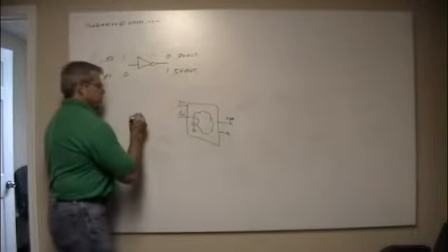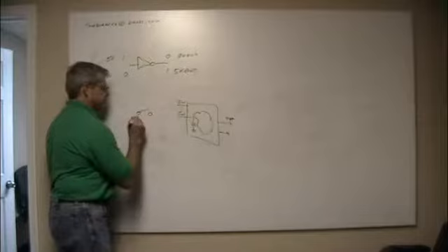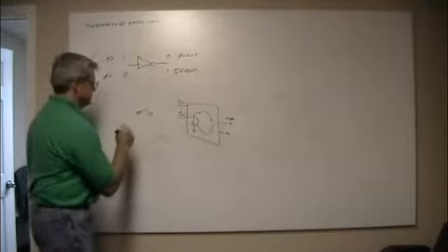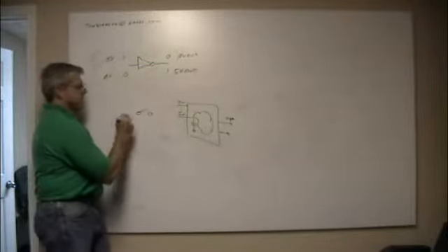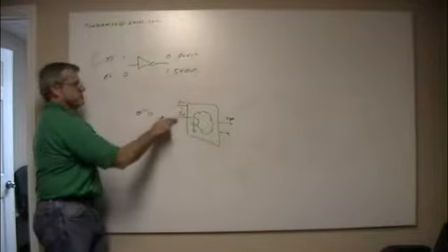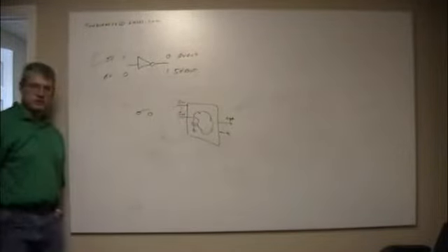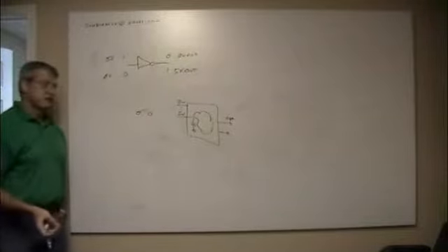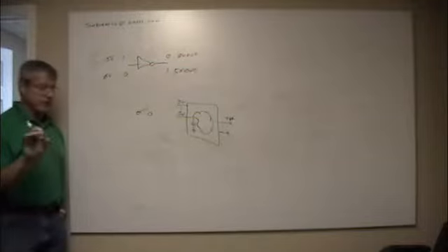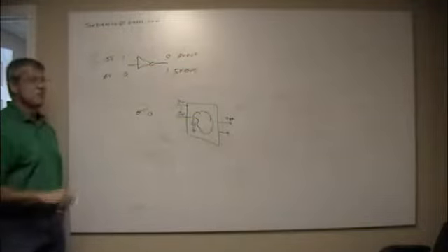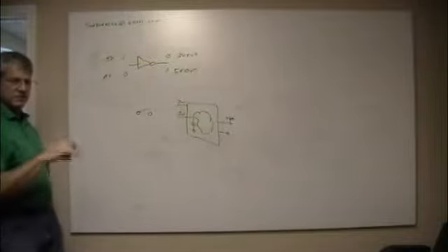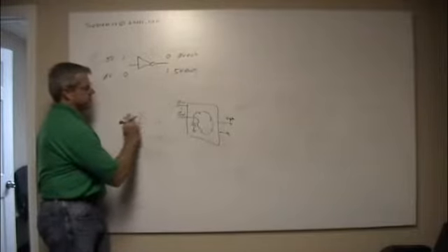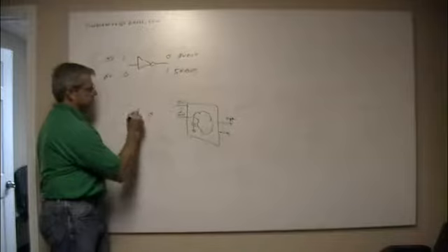So if I were to hook a switch up to this, quick conventions, you can do this either way. What I want to get is 5 volts or 0 volts going into the thing, or depending on the logic, there's 3 volt logic, 2.5 volt logic, 1.8 volt logic. I've even seen relatively recently, on the output pins, 0.8 volt logic, really low voltage levels. So I have to switch power. There's 2 ways to do this, practically speaking. I suppose I could do this, right?